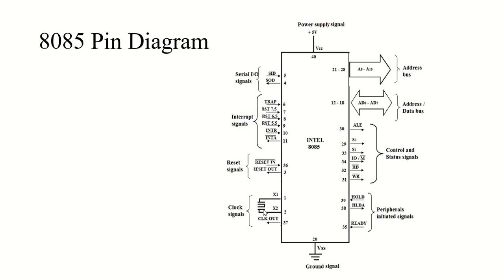Since negative binary numbers are represented in the 8085 CPU in standard 2's complement, this sign flag will be used as an indicator of that. So if MSB is 1, which means my number is negative, then the sign flag will be activated.